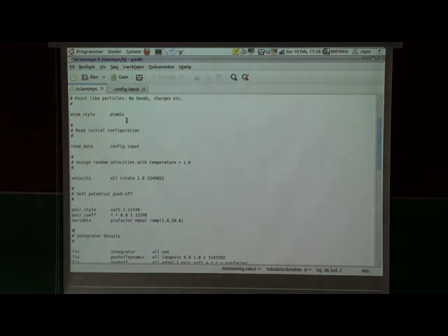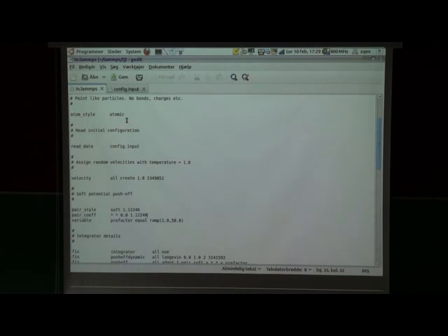So this is just a short introduction. With 5 minutes, I don't want to go into detail, but this is just what LAMMPS looks like. You need to specify how to run the simulation. This is also a single text file. For instance, I specify atom style atomic. Atomic means that you have beads with positions. If you want polymers with angular interactions and charges and so on, there are other styles for more complicated things. Always use the simplest style because then you don't waste CPU time.